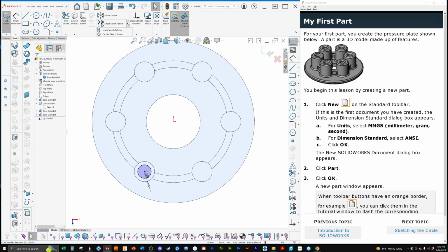Oh, there, there. We got to get it set to 6. Then we can do our extrude. And the same thing. Ideally, we want to extrude cut up to a surface, just to guarantee that it always goes through.